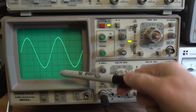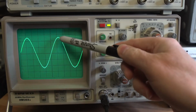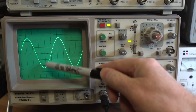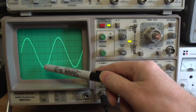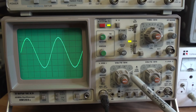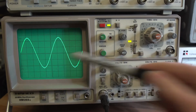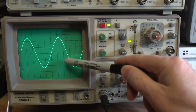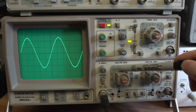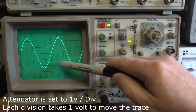It can tell us the amplitude in volts. How big is that signal from the trough to the peak, or if you like, the negative point to the positive point. The difference, the height, is the amplitude or the voltage, peak to peak voltage. And we determine that using the attenuator control, which tells us how many volts it takes to go from one division to the next. So each division, it's actually a square centimeter box, is determined by the voltage coming in through the attenuator. At the moment it's set to 1 volt, so it takes 1 volt to get from one box to the next.